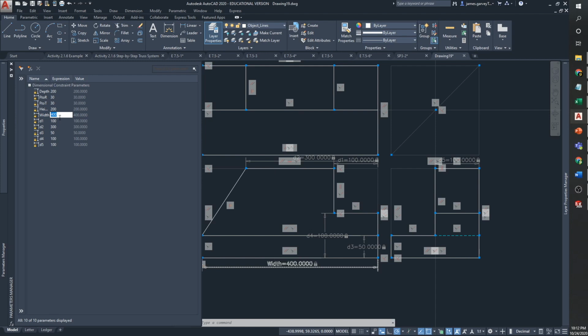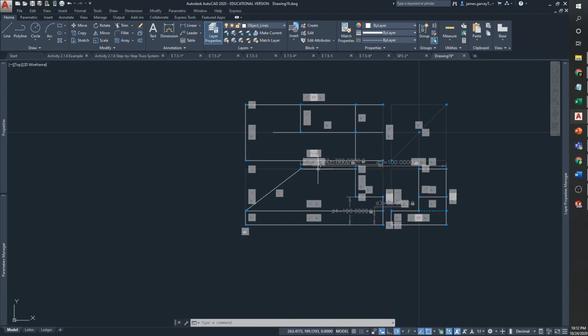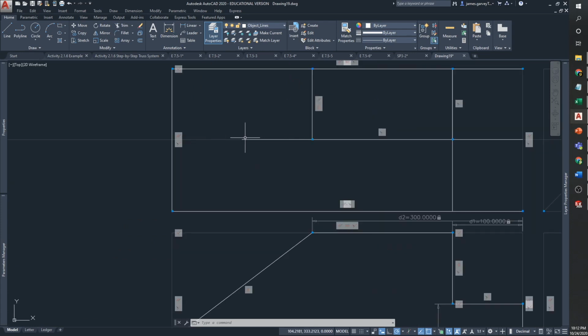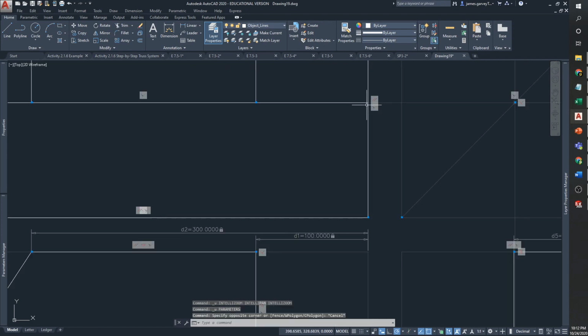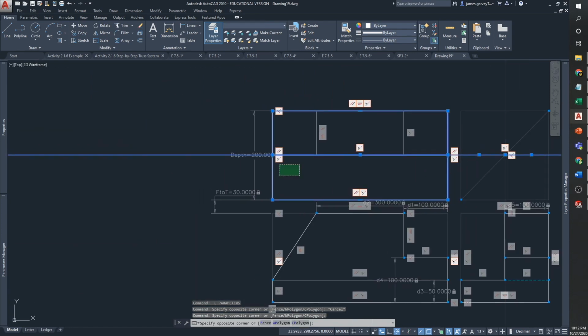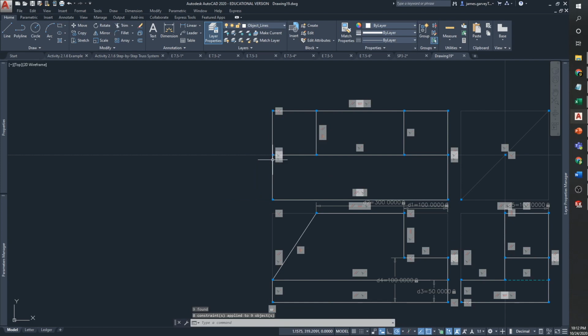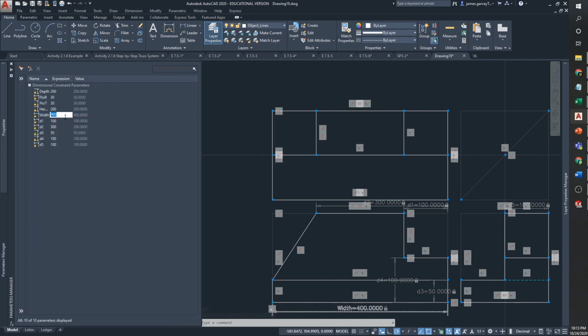So let's change our overall width to, let's say, 500. And okay, so there's a couple issues there. So Control Z, and you can tell where the problems are, where you don't have those blue dots. So I can select that spot and that spot, some of these edges here, and auto. So that added my coincidence dimensions I needed. So let's try that one more time.